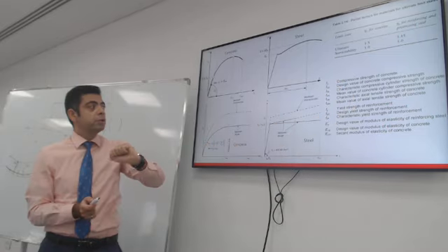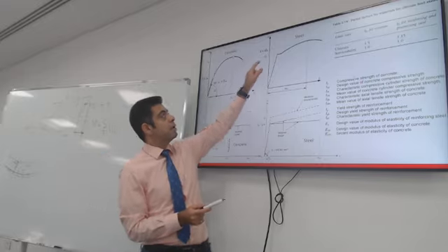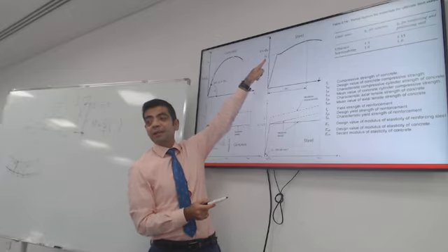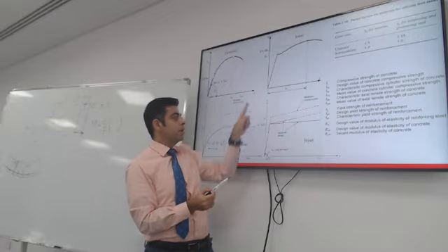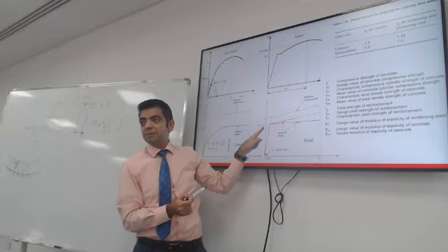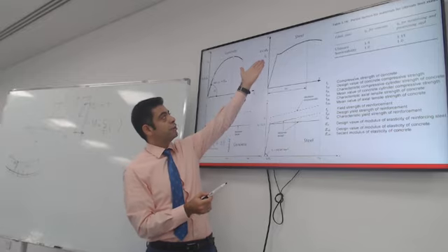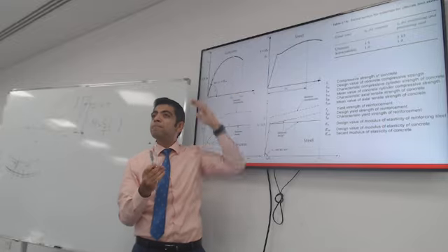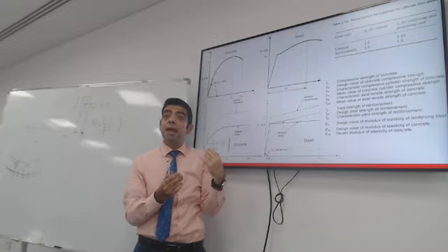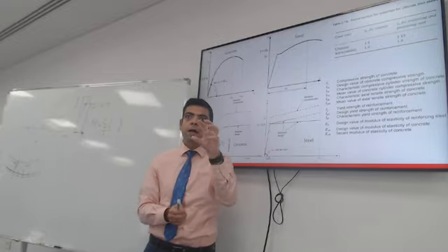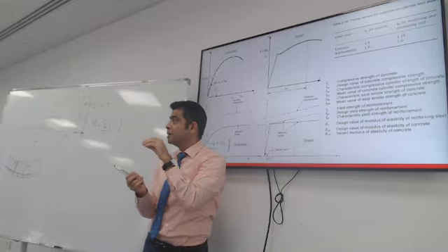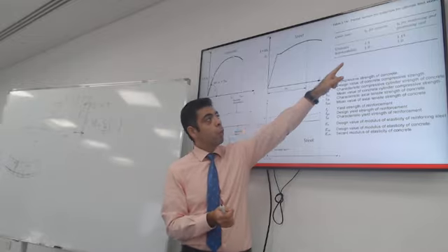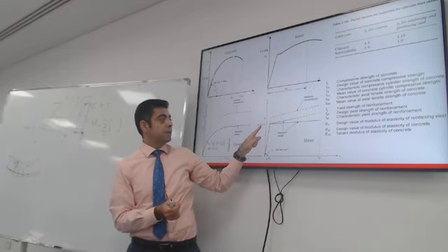So how do we use these factors? Rather than using the characteristic yield strength of steel, you divide it by gamma S. So if F yield is 400 or 500 MPa, you don't use that number in the design. You reduce it. You reduce it by how much? Divided by 1.15. This is this number.